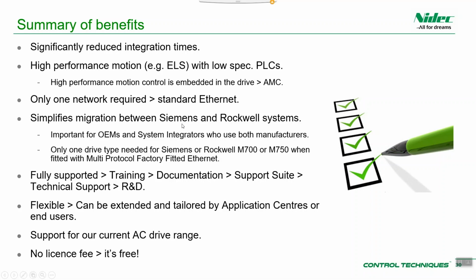You've got simple migration between different third-party PLC products. Okay, so because the motion interface is common between Siemens and Rockwell, and so is the drive, it means if you've got a customer base that generally swaps between Siemens or Rockwell type systems, as those are some of the main players for third-party PLC products, you would only actually have to learn one motion interface and be able to work with both of those systems and not really have to learn anything new, because it's a common interface between those two PLC environments.